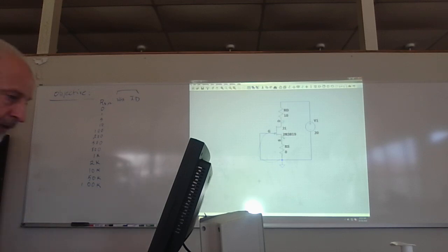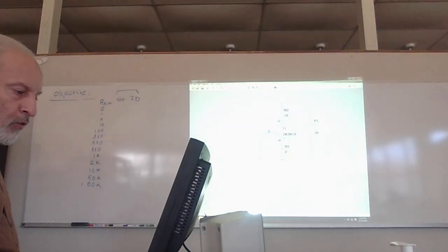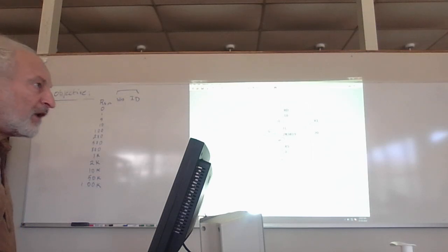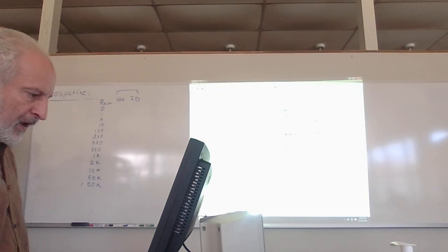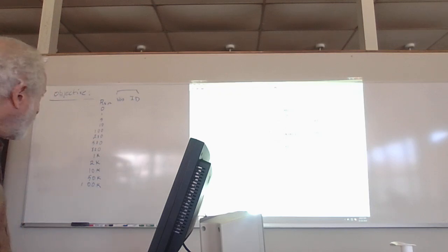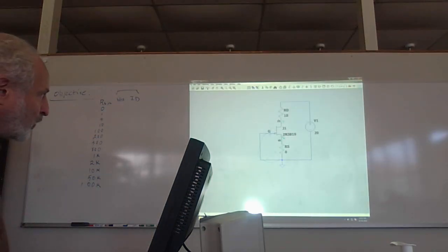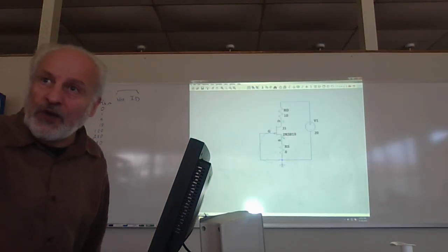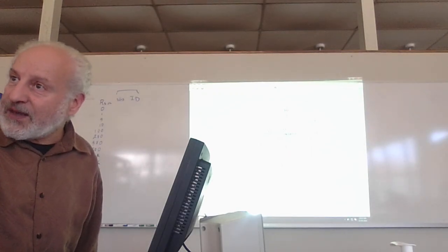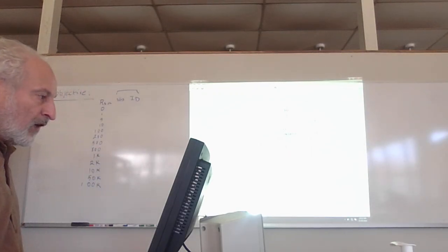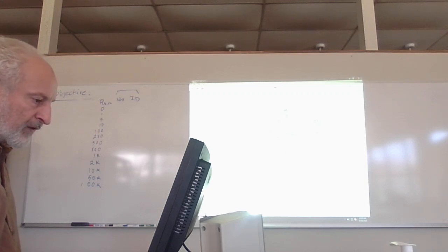Okay, so at 0 ohm, let's see what happens. What did I just say? That this point is the same as ground, so is this one. So VGS is 0. And since we're in depletion mode, we'll get IDSS. Does that make sense? So if I run this, DC op, and say OK, there you go.